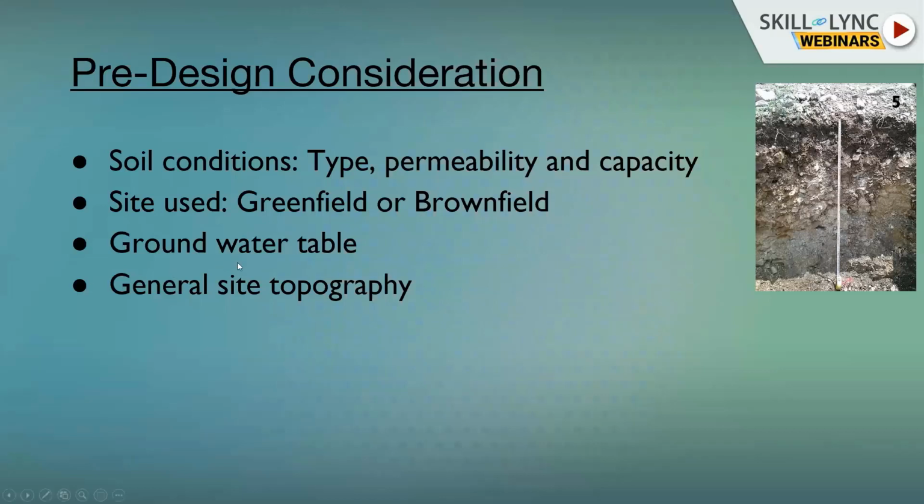Then the groundwater table, it has a major significance as discussed in the infiltration, and also if the groundwater table is very high, we cannot provide SuDS there because it can rise up and create some disturbances to our calculation and the design.